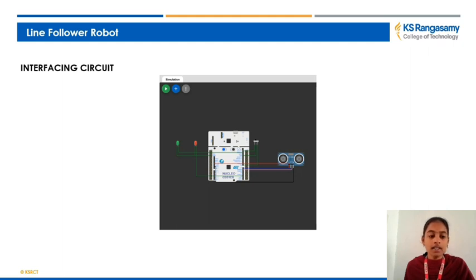The red LED is connected to one of the Nucleo GPIO pins through a resistor to limit current and then to ground. This LED is likely programmed to turn on when the measured distance falls below a certain threshold, indicating that an object is close. The green LED is connected to one of the Nucleo GPIO pins through a resistor and then to ground. This LED is probably programmed to turn on when the measured distance is above a certain threshold, indicating that the area in front of the sensor is clear.